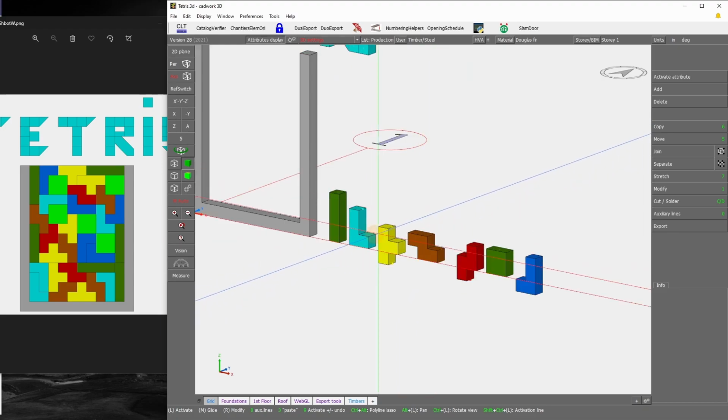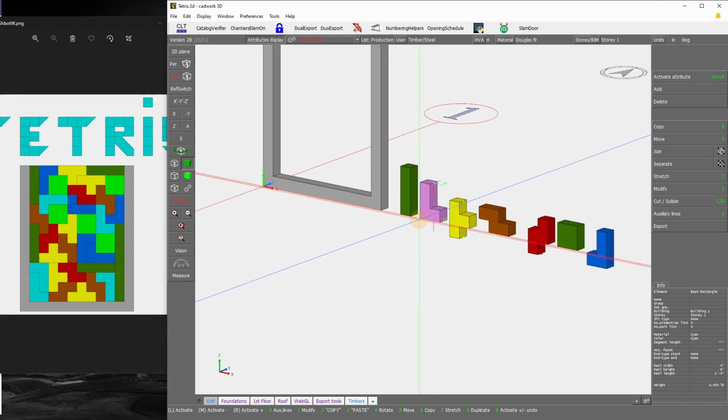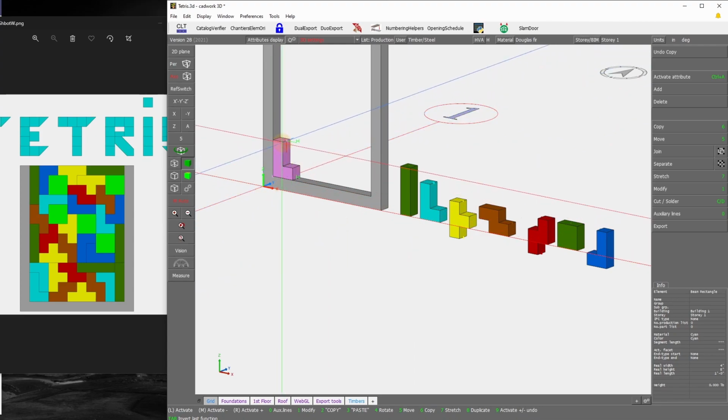Just to remind you, when you select an element with your left click, always try to select a point that will be useful for the future location where you want to move or copy your element. In that case, I want to place first this L-shape cyan element, from the bottom left corner, and I will just copy it with 6 right at that location. I could directly place the second one, using that point, for example, this one here.